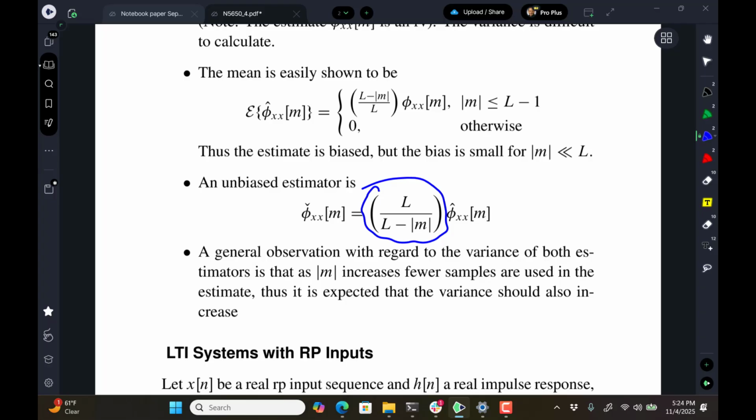But in the case of this autocorrelation function estimate, what I learned a long time ago, and I still have those books in my collection, is that using the unbiased estimator turns out to not be as good a practice because you can get unstable results. So using the biased estimator was actually recommended in some of the algorithms I was studying.